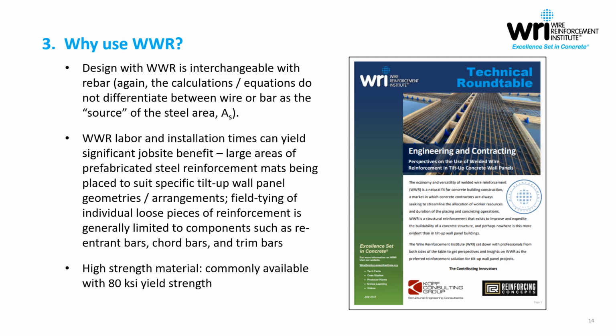But the real benefit and the reason, honestly, that welded wire reinforcement exists in the first place is for the on-site advantages. Labor and installation time can be improved upon. You're reducing your labor, you're shortening your installation times, because you're putting down large areas of prefabricated steel reinforcement, and they're being placed to suit specific tilt-up wall panel geometries.